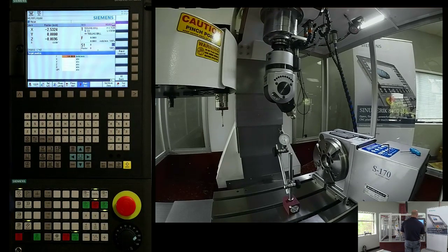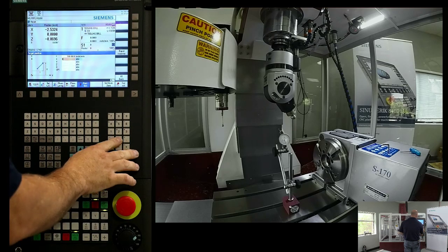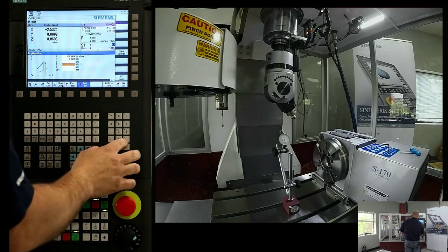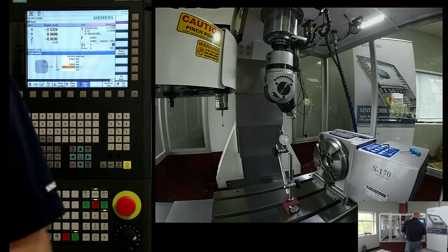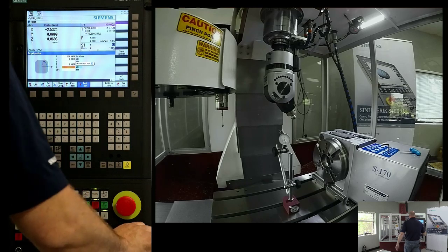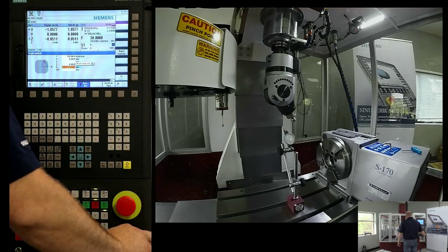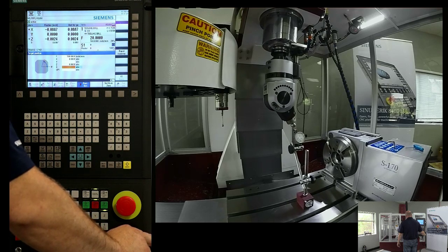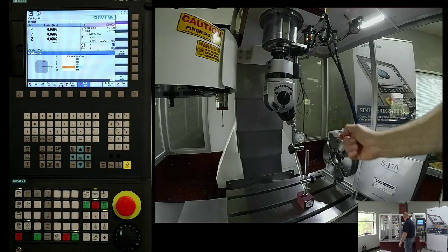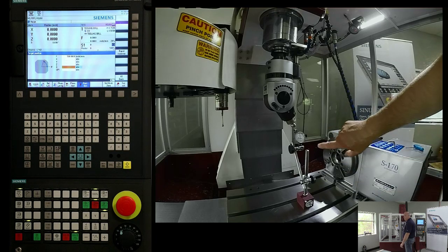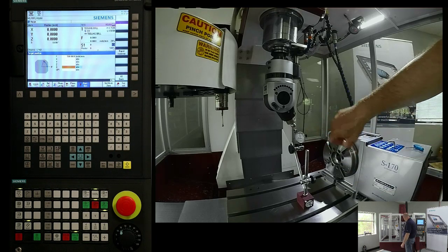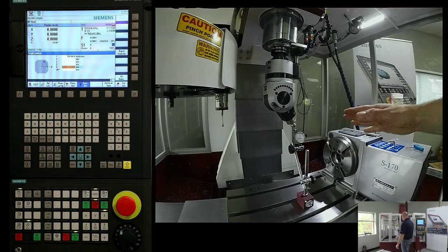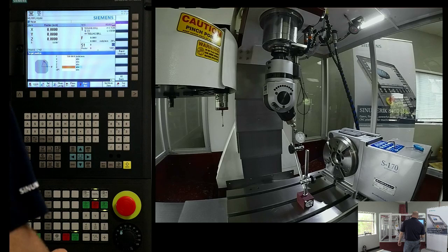Now we're going to position, and this is why I set that secondary 0. I can just position to 0, 0 for all my linear axes. Cycle start. And where the machine should end up is, if I was to draw a theoretical line from the center of the sphere straight down to my indicator, that's where it should sit. So I don't know if you guys can see it, but I'm within a few tenths of where I was at. So what I would want to do then is repeat this measurement for a couple different angles.